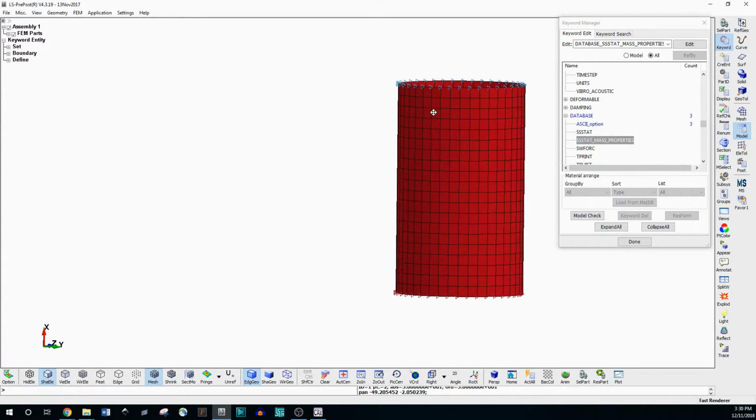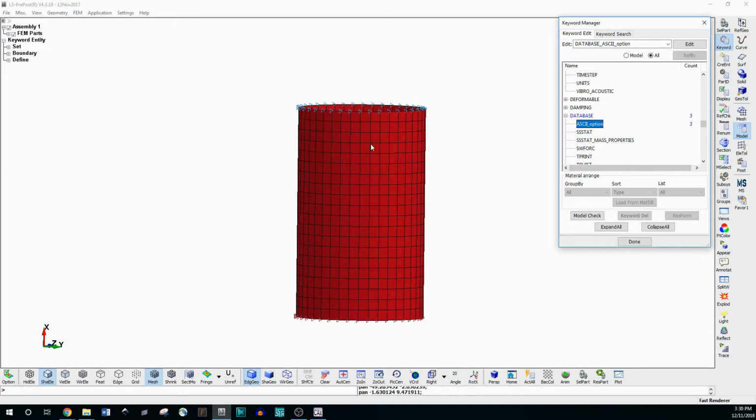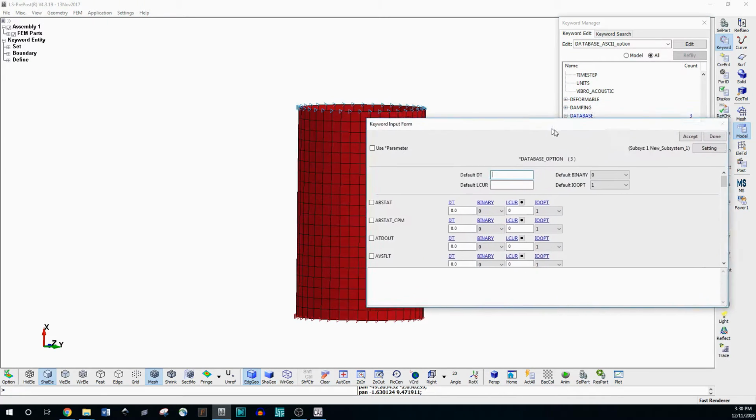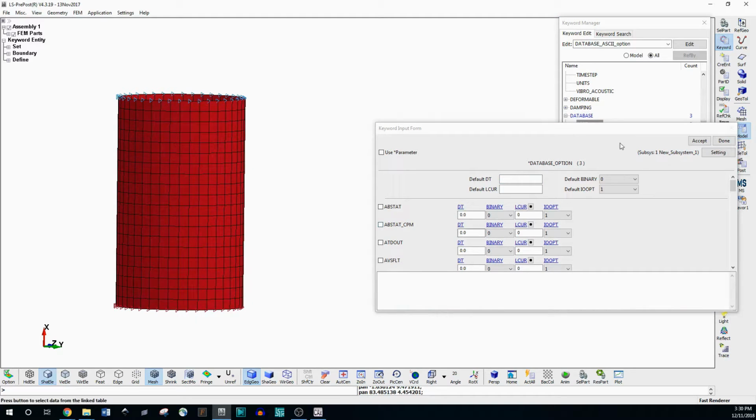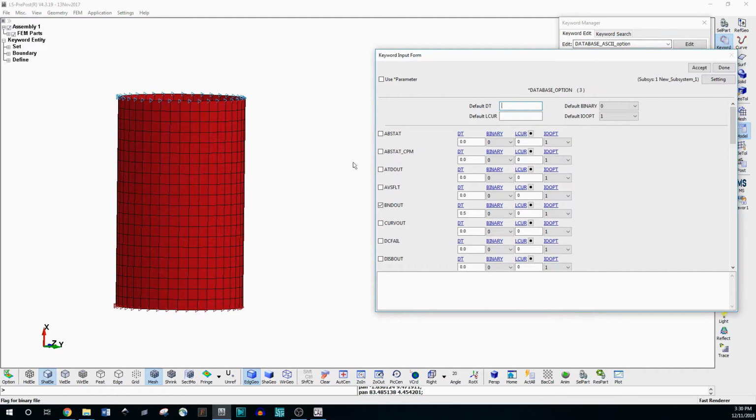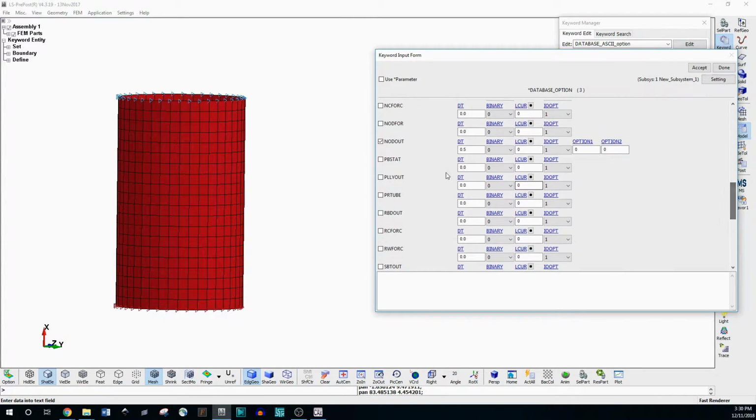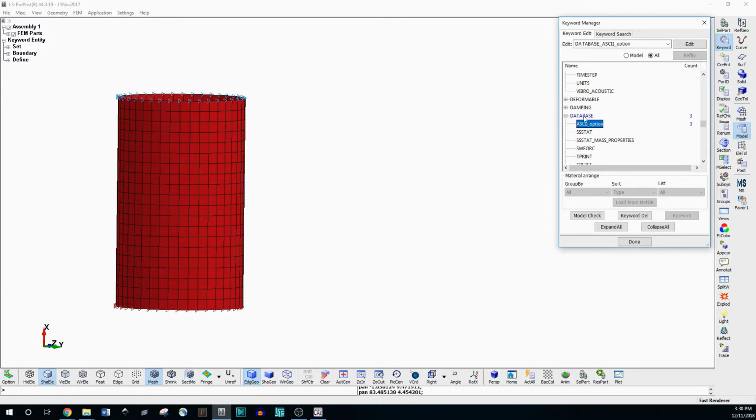One thing to remember though is each of these outputs needs to have a corresponding thing in the model, and what we need to do is define a sort of sensor for tracking this set of nodes, because we want to get the node outs here. But in order to get these, you have to define it in database history.